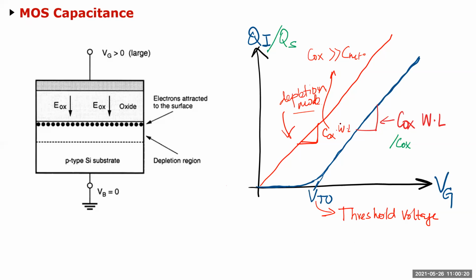Yesterday we were calculating this distance as about 180 nanometers, so you get orders of magnitude improvement in your Cox by using the MOS thin oxide. But the downside is your breakdown voltage is also lower. If you're using a MOS cap at 1.8 volts, then your breakdown is 2 volts. You can't go higher than 2 volts, which is fine because most of the time you're using it inside your transistors, which have to be limited to 2 volts or 1.8 volts anyway.